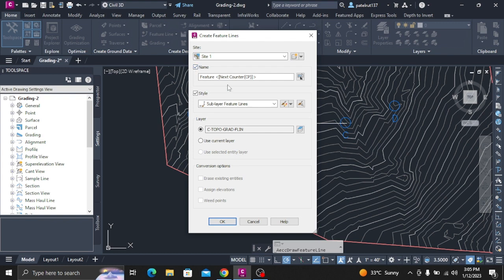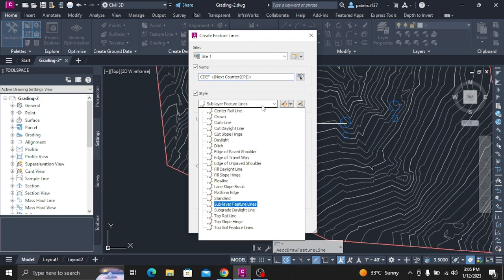Insert an elevation point on a feature line. In the Grading Elevation Editor, click Insert Elevation Point. Move the point to a location near the middle of the feature line, then click. In the Insert PVI dialog box, optionally move the elevation point to a specific station. Click OK. The point is added to the table in the Grading Elevation Editor, where you can edit the station, elevation, grade, and length, distance between points.